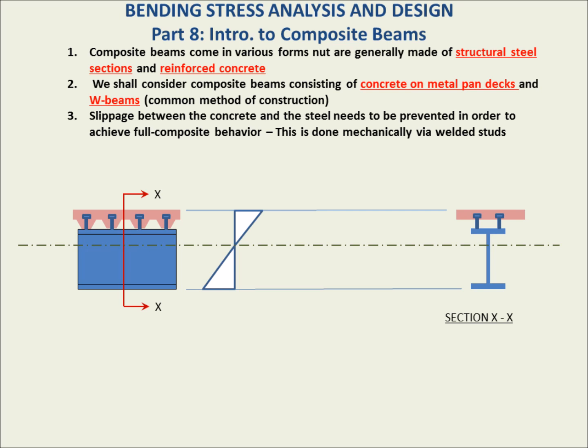Now we can write here that in the elastic range, the flexural stress is equal to the moment divided by the section modulus, or MC over I. Now at this point, we would want to go forward and draw our stress diagram. And in the elastic range, we're seeing here an experimentally verifiable strain distribution that is a linear transition from tension to the compression zone. So we would expect a linear stress diagram.